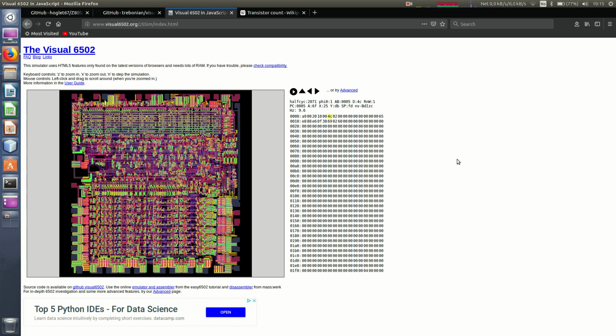So I've come to a point where I have a lot of artwork I want to simulate in the VIC2 dieshots that I'm vectorizing, and I found this cool project which has a simulator for Z80. But first let's have a look at Visual 6502. The problem I have is going from this to a transdef file. That's a list, or a net list, by transistor and all the connections in between.